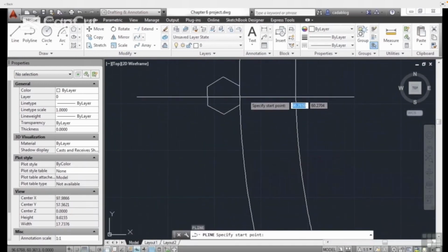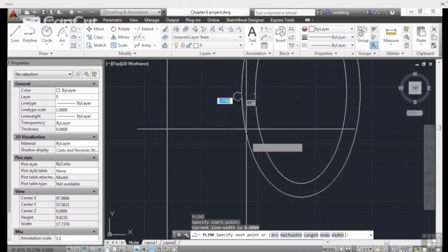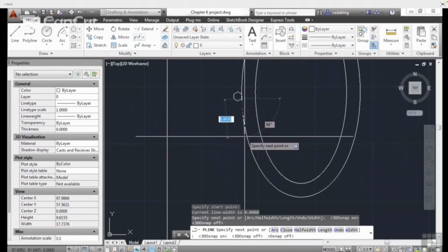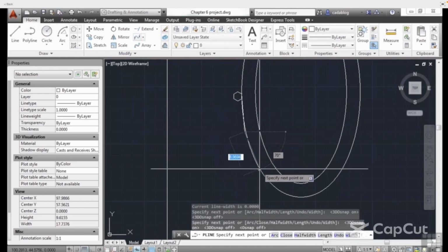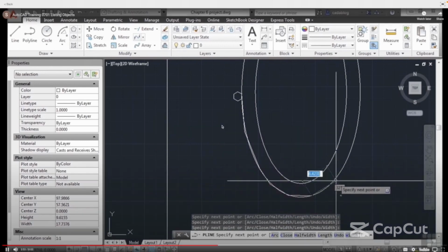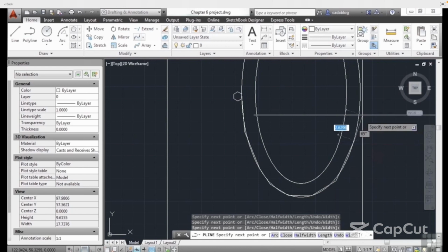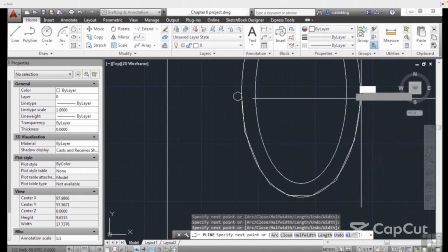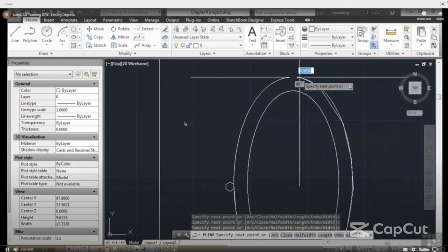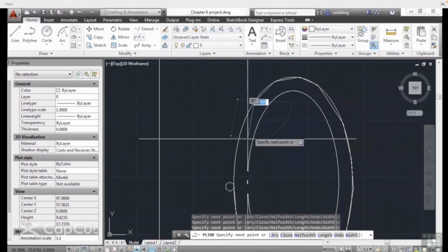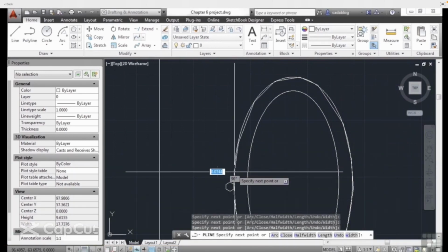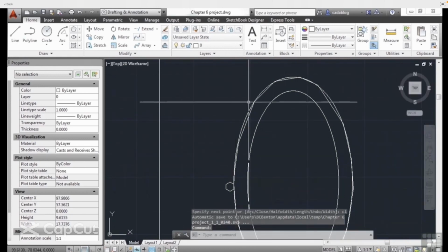And we're going to start from this point here. And we're just going to draw different shapes. Turn off your O-snaps and then just draw somewhere around where this ellipse was. We don't have to be exact in this case, but if we did, we can use the near O-snap to click onto different places along our ellipse. There are many times in CAD in which things don't work the way you expect them to, and so you have to improvise.